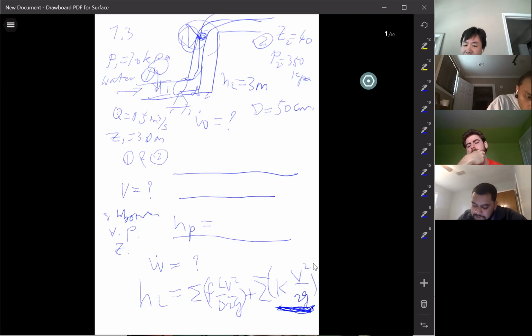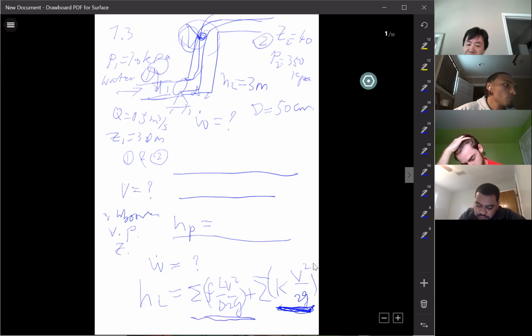We'd have to use the roughness of the pipe. If there's a strainer in it or anything like that, that'll be counted in the K, right? No, that's just the roughness of the pipe. That will be counted into the frictional head loss. Remember, you have two components in the head loss: frictional loss and minor loss. If you're talking about the surface roughness, everything is frictional head loss. It will be included in F, the friction coefficient.